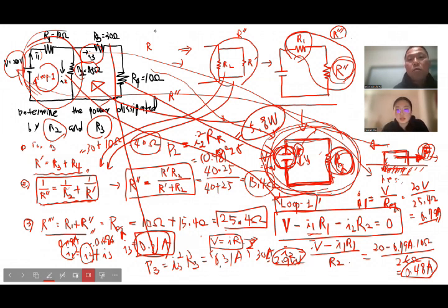Yeah, there's no holy Bible to solve one problem; there's not only one absolute way to solve it. There are multiple different ways you can apply. This is just one typical way to solve this kind of multi-connection DC circuit problem. You can also find the ratio of the current with respect to the resistors, once you find R prime and R double prime, and then directly apply the power rule, I squared R, to estimate the power dissipation of that component.